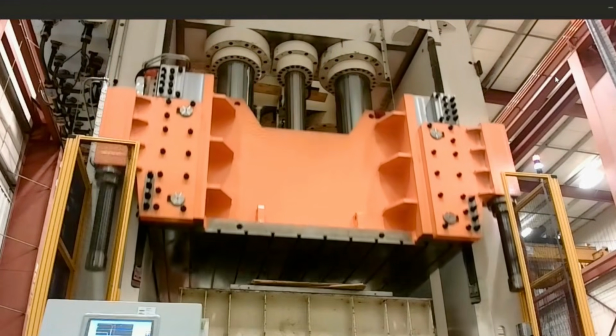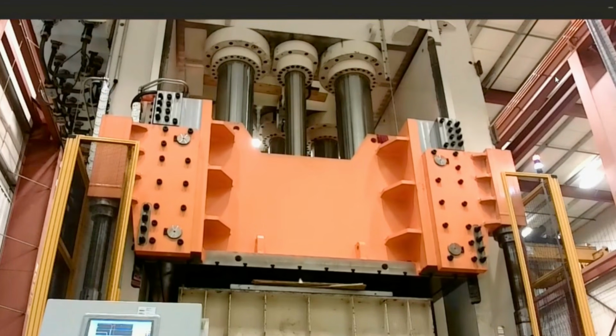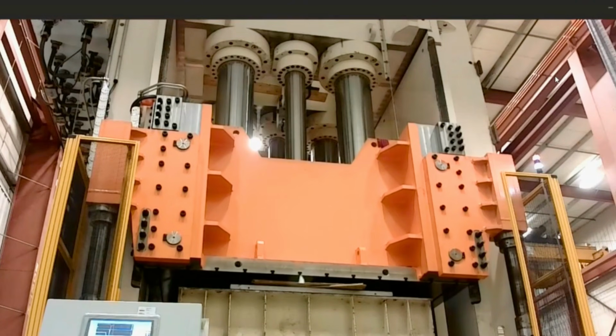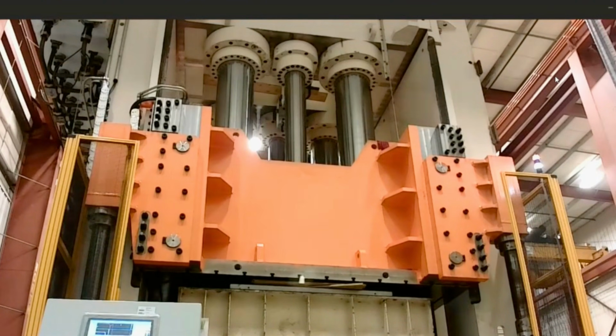Not every press application requires this level of control. The decision depends on what determines the final part, the tooling, the press motion, or a combination of both. So closed loop control is a more expensive process. It is more accurate, but using it requires a lot more tuning and a lot more control. So your expenses to run the machine are going to be a little higher. Your expenses to set up the machine are going to be a little higher, but in the end, it gives you a better product.